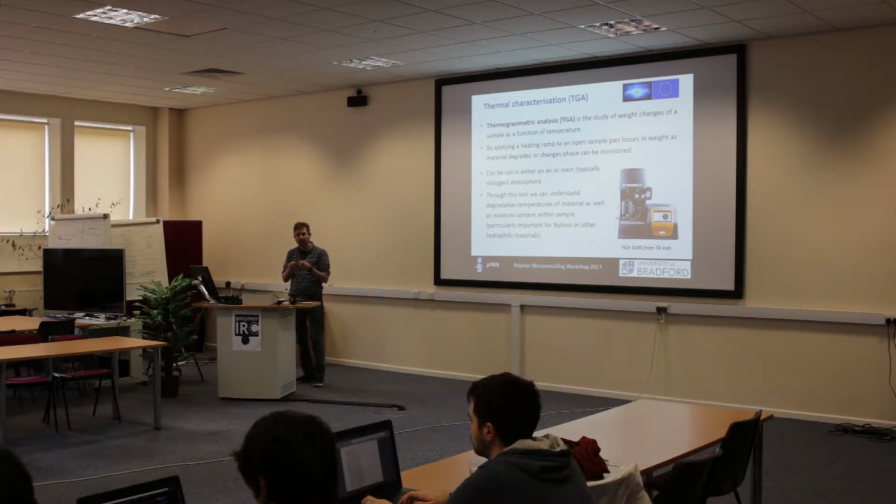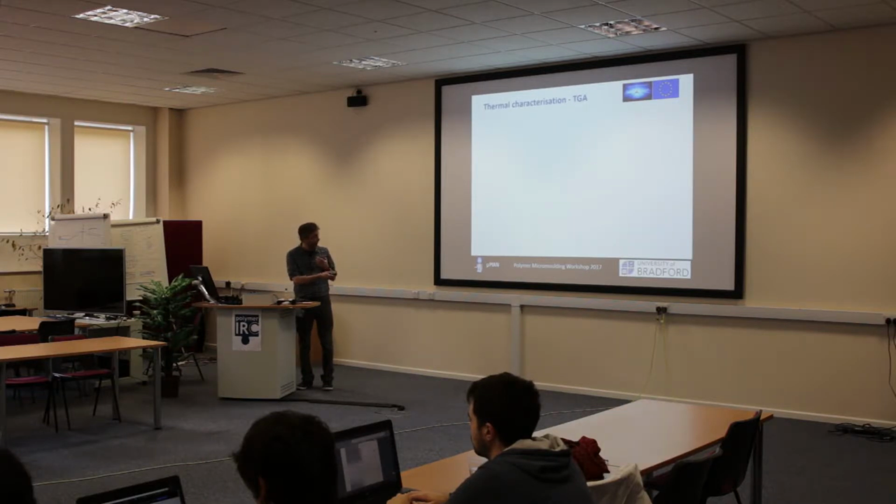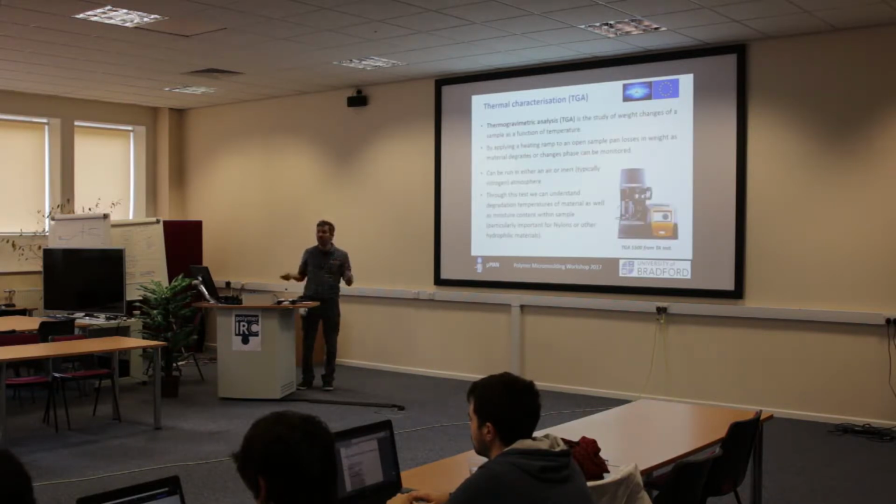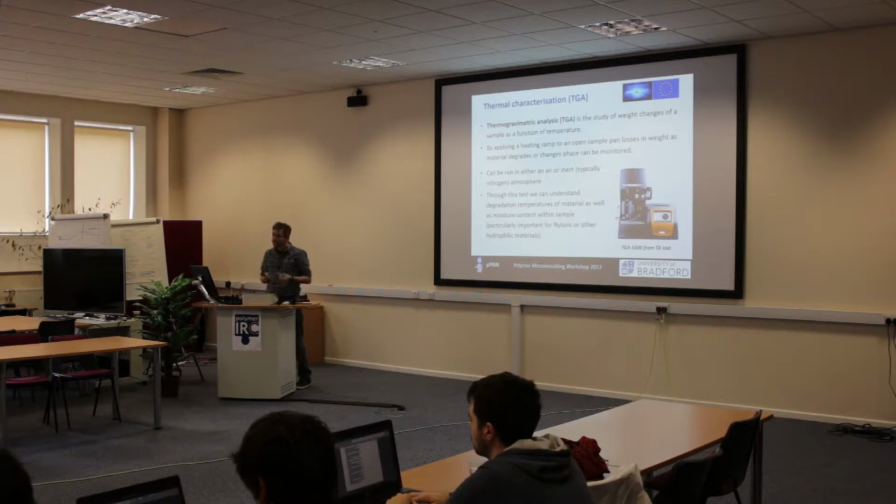For instance, nylon may take on 2% of water. As soon as you go through that transition at 100 and all the water starts steaming off, you can imagine what you get in your nice, steady, controlled process for hundreds of thousands of pounds: bubbles of steam blowing out. You'll never get a good product out of that.